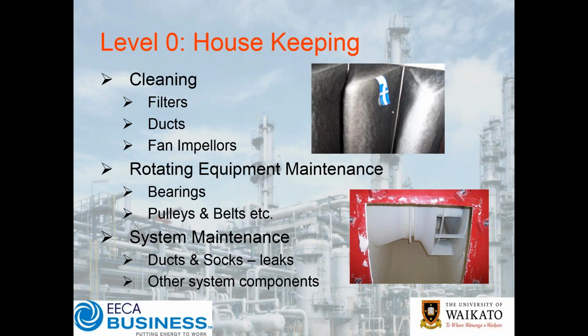Are you sucking cold air into a system that you perhaps don't want cold air in, and is it causing cold spots, or conversely hot spots? Never mind energy loss, is there a product quality or a safety issue associated with that? It's very common, and these basic things are relatively easy to get right.